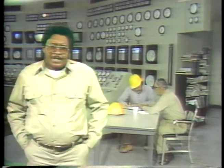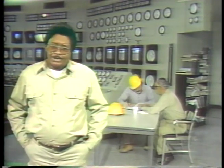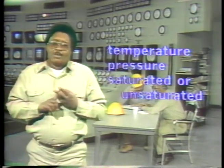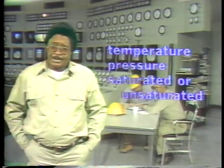In order to use the tables accurately, you have to know something about the process that you're checking. There are basically 3 things that you'll need to know: the temperature, the pressure, and whether the process is saturated or unsaturated. If you know 2 of these properties, the steam tables can give you the 3rd piece of information.